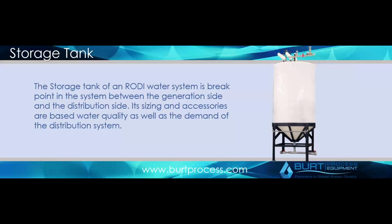As we talked about earlier, high-purity water systems are divided between two major areas. You have generally your pretreatment RO side, which may or may not encompass part of your DI treatment, and then you have your loop and your polishing side. The storage tank is the break point between the two of them, where you have your generation or makeup rate versus your recirculation or distribution rate.